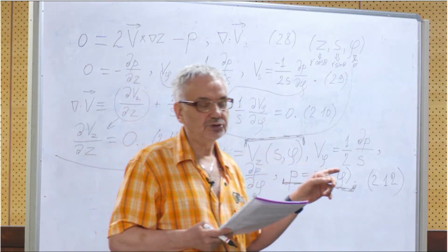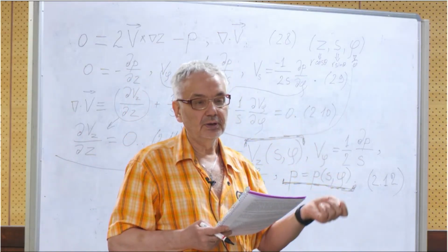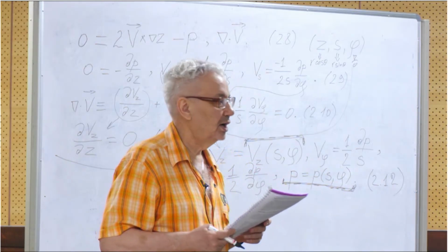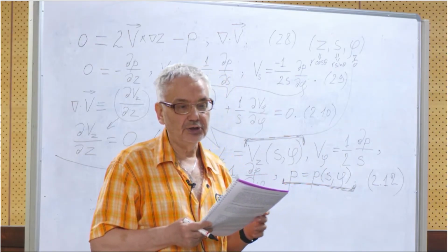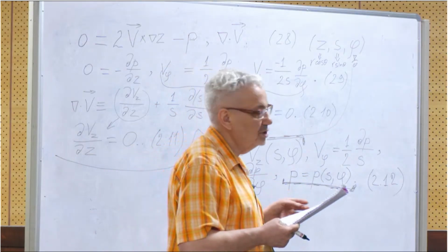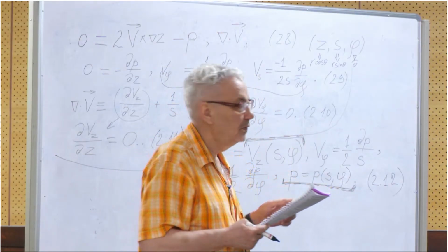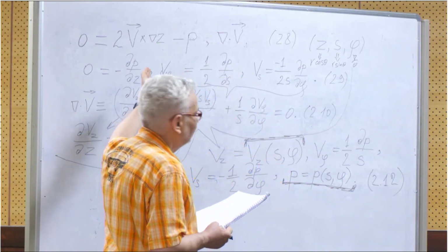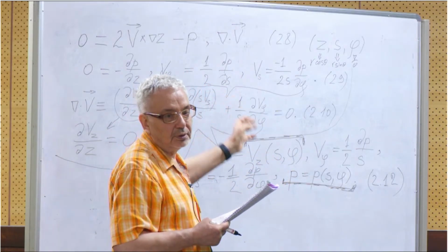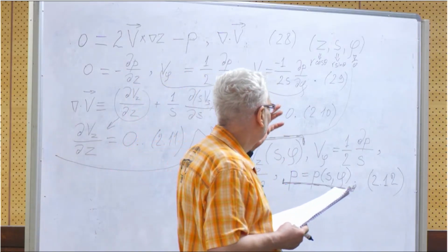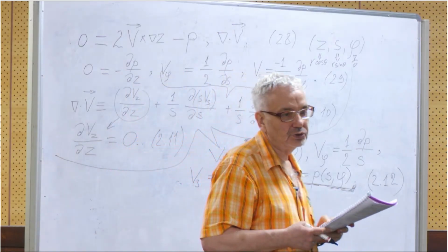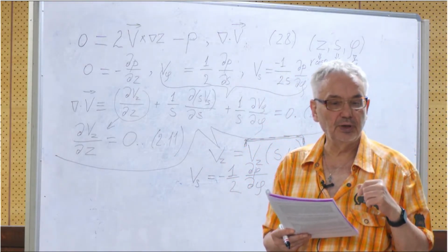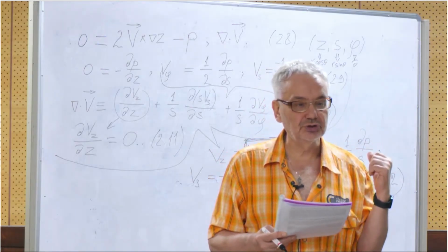We neglected viscosity, so we omit one order of magnitude, which removes the extra boundary condition. Here the situation is reversed. We have the highest order differential term 1, just 1, and again we have 3. So we should reduce the number of boundary conditions to satisfy this reduced system.